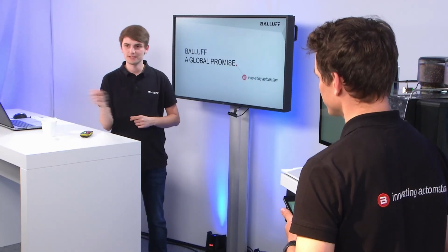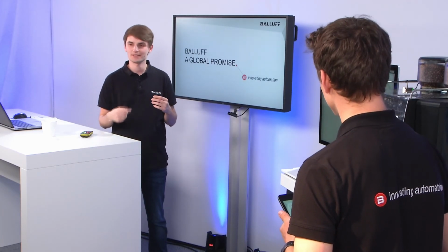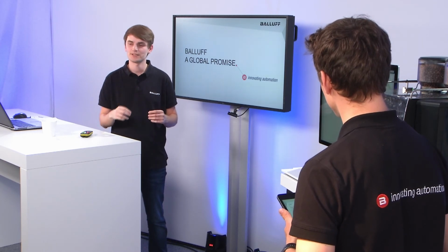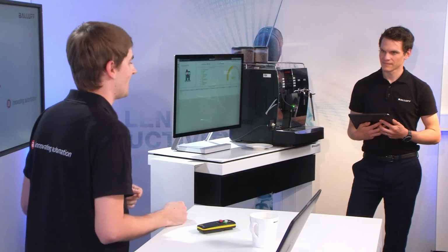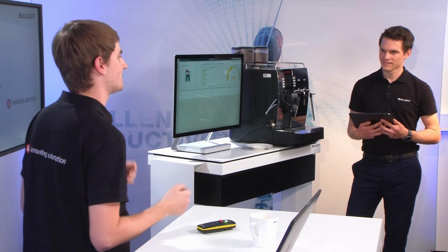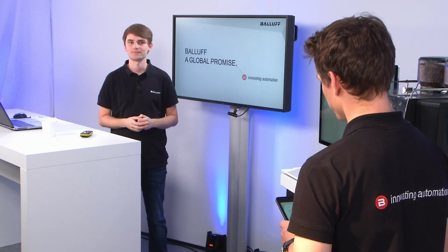You place your sensor on a rotating axis or other locations, collect this data, and then start your training process, and now you're able to say, okay, according to my vibration, I'm currently with a likelihood of 80% in this state. But you have to keep in mind, you can use this only if you know the states of your machine. The other thing is you can use an anomaly detection system, so you only need to know one state of your machine.